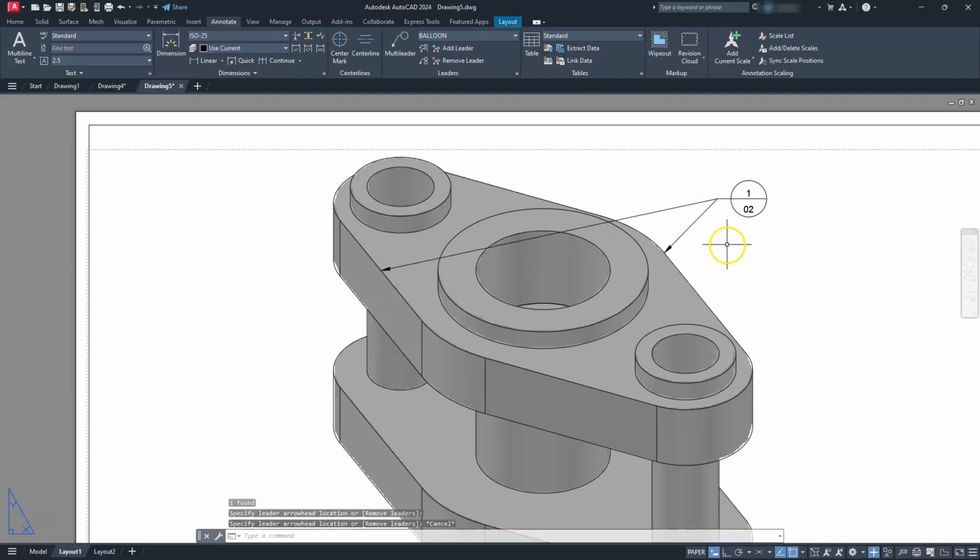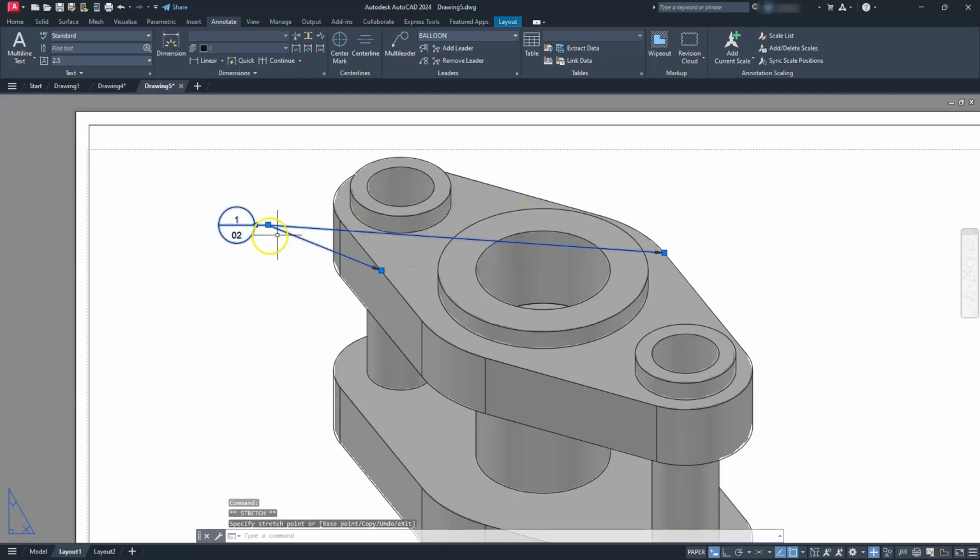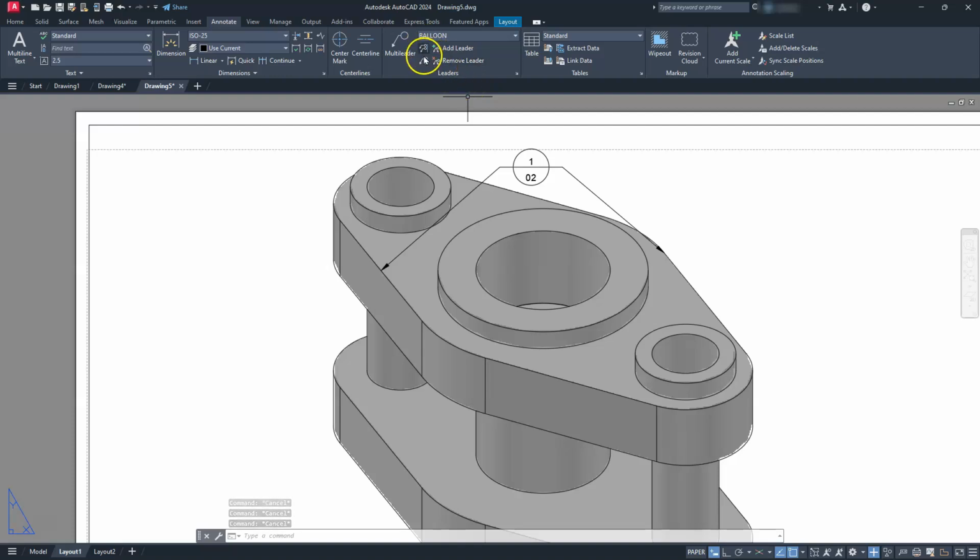With multi-leaders, a really neat feature is that if I select here, and let's select the square, and take a look at what happens when I drag this along the other side, you will see that it will automatically adjust that landing. Say if I wanted to put this in the middle, it'll grab them and put them on both sides. Other things that I can do with them is I can also stack them, and I can align them, and that's what these options here are telling me.